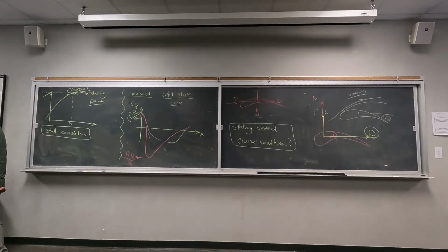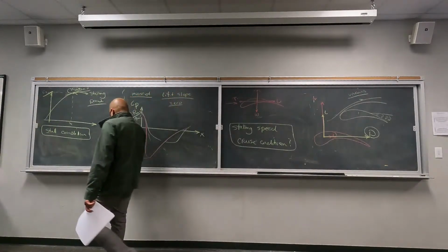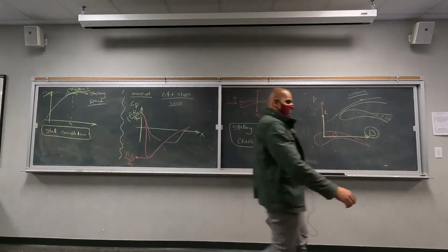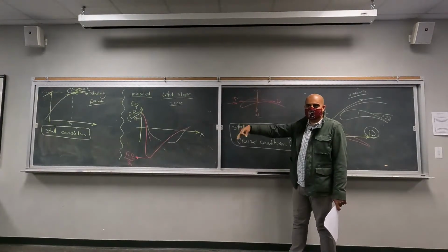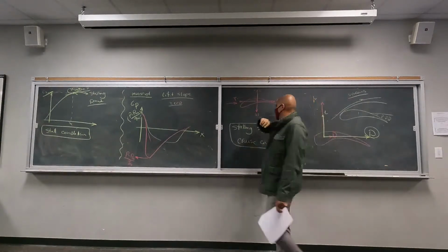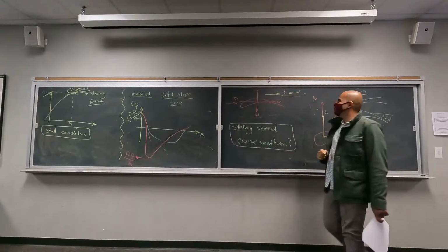What do you think the relationship between these aerodynamic forces should be to maintain a cruise flight? Lift equals weight, right? Because you don't want to have any excess in any direction, in the y direction. If your weight is higher than lift, then your elevation will decrease. If your lift is higher than weight, then you will start pitching up, right? That's the idea. So for cruise condition, lift has to be equal to weight.